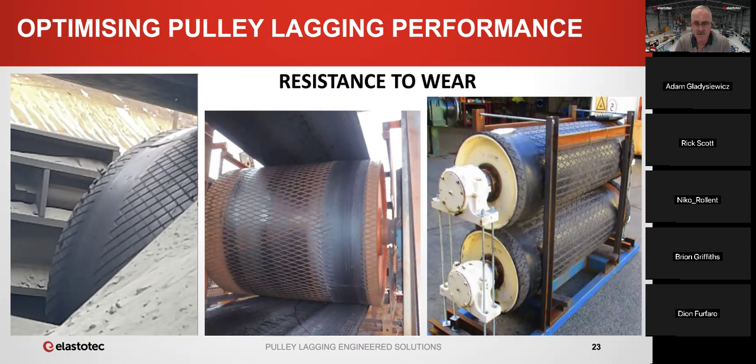These photos show examples of the sort of wear that you can get on non-drive pulleys. The photo on the left and the photo in the center are from a turnover conveyor. And the photo on the right is from a conveyor operating with PVC solid woven belt that had stretched on the edges.